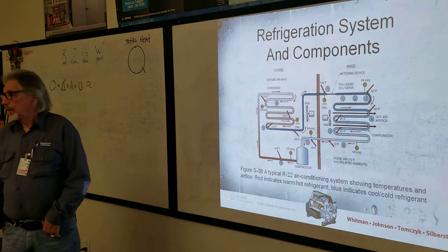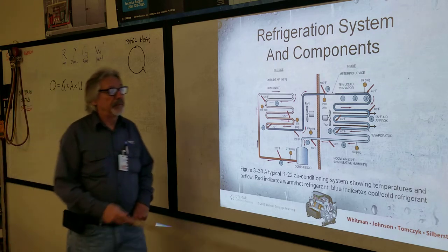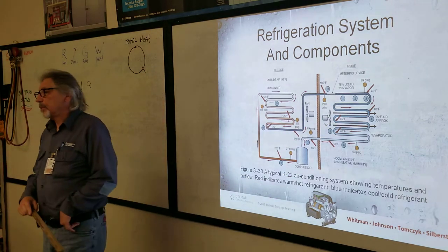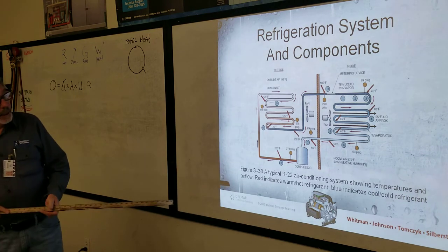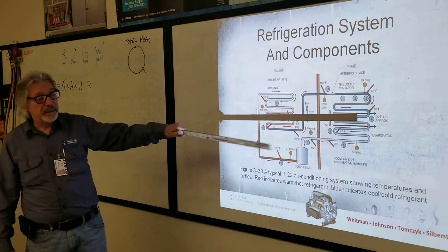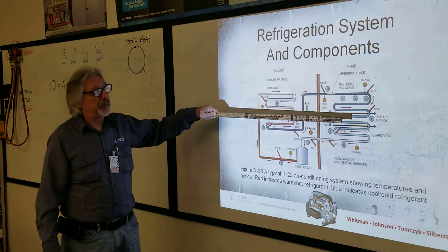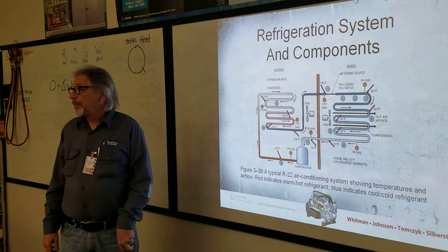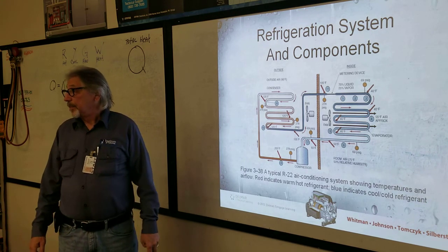Getting that so far? That is the cooling effect of the evaporator coil. As the refrigerant evaporates or boils, it boils at 40 degrees, or it's changing state. Same thing, it's boiling, or it's saturating. Same thing.